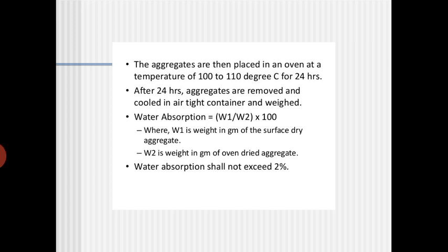And normally, your water absorption ratio is going to increase if there is a higher elongation index or flakiness index, or if you are exposing more surface area to absorb the water. In that case the moisture content or absorption is going to increase, because more surface area is exposed to the water. Or if we have more cracks inside the aggregates, then of course the surface in the cracks is also going to be exposed to the water.